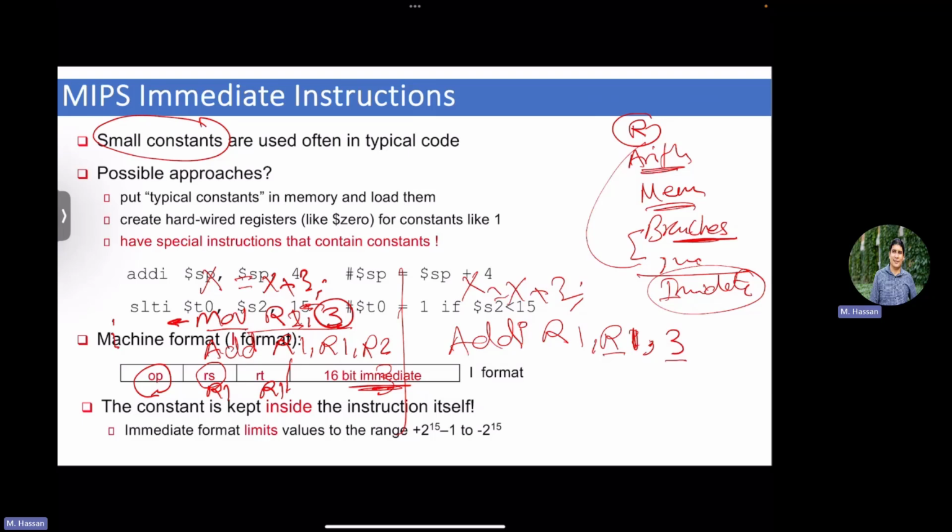We will discuss in a second what if my application has a larger one. So we'll follow the same philosophy of the jump. Yeah, okay, that's exactly the slide that I guess answers your question. What if I have constants or immediate values that are larger than 16 bits? What do I do? Well, simply you use the upper and lower of a register, right? So you say, I want to load an upper immediate to a register and then a lower immediate to a register and then do an OR operation. So what you do here is basically called load upper immediate.